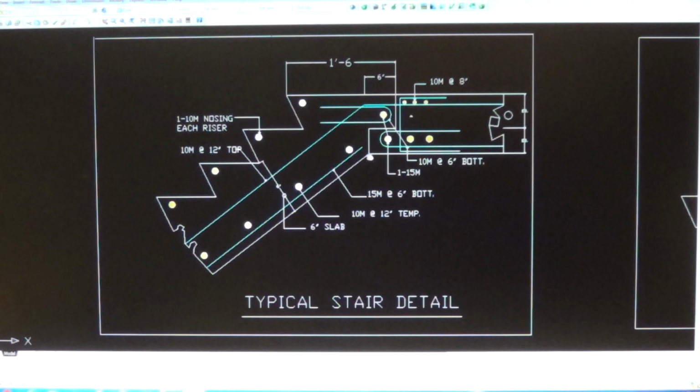Okay, the line here, see the nuts there? That is for the prefabrication of the precast concrete stairs when it is fabricated outside of the site. So we have to pour the concrete in this shape here with the nuts right here, and that distance there is 6 inches. When this is fabricated outside, this landing is going to wait for the precast concrete to arrive and install it right here.